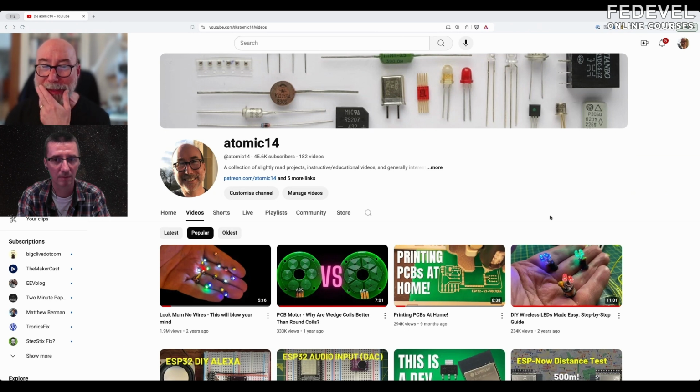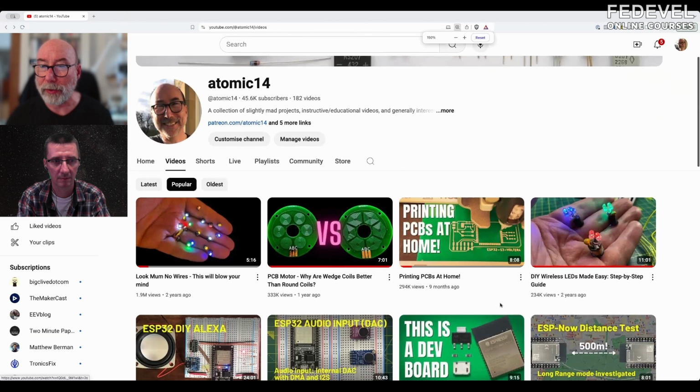Is it good? It's okay. It's quite fragile. If you have connectors and stuff, eventually they will snap off, and it wears off over time. So you can't use it for anything that's under mechanical stress. It is pretty good, though. This was an ESP32 board, so it's good enough for quite small components. It does quite fine pitch, and then it also prints the solder paste as well.